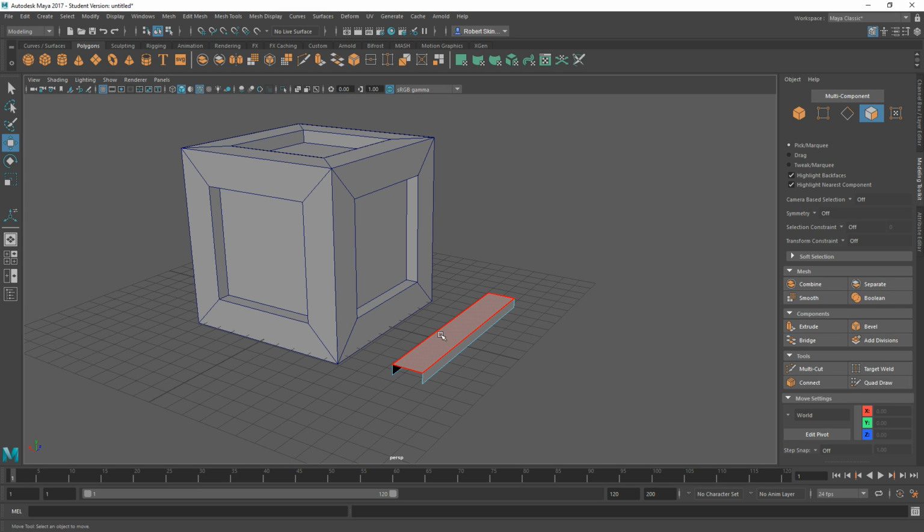And if each one of them is not optimized, the polygon count just increases and increases and increases, as does the work required to unwrap, as does the texture in memory. Everything like that increases. And over a period of time, what you end up with is a massively unoptimized object, which might not seem like a problem in itself. But if I was creating, say, Crate Simulator, and I had 300,000 crates in a scene, suddenly we're not talking about tens or hundreds of polygons. We're potentially talking about hundreds of thousands of polygons that are being loaded into memory, have got texture applied to them, but are not actually doing anything.